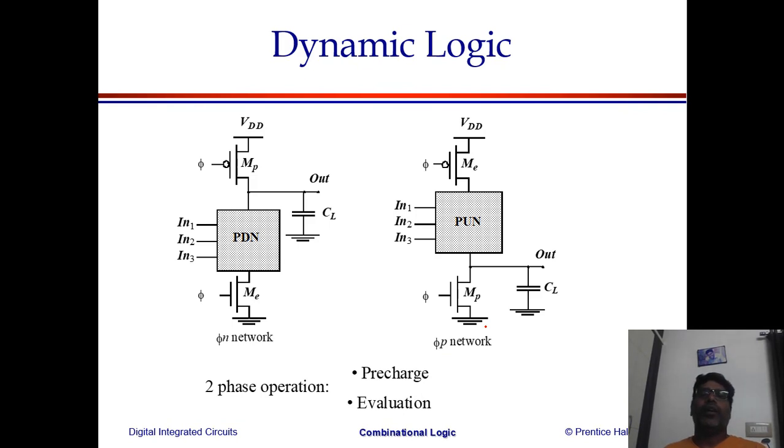The next and most important type of logic style is the dynamic logic style. Coming to dynamic logic style, this logic style will be using a clock. I am trying to come up with a solution wherein there shouldn't be a static power loss, but at the same time I need a minimum number of transistors and a controlled operation. Keeping all this in view, we come up with a different logic style, which we call the dynamic logic style. Here the number of transistors required is n plus 2.